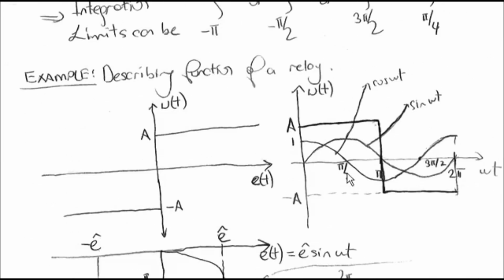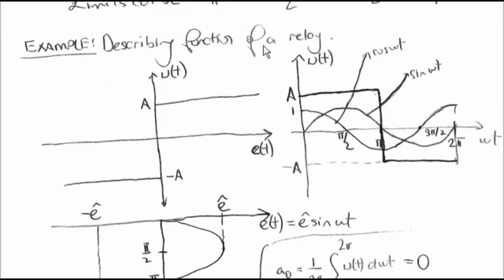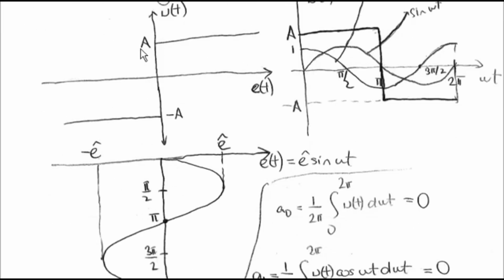Now we are going to be trying to calculate our first describing function. Here we are going to calculate the describing function of a relay. A relay is just a switch, and this is shown by the sign function like this here, and it takes the values plus A for positive inputs and minus A for negative inputs.